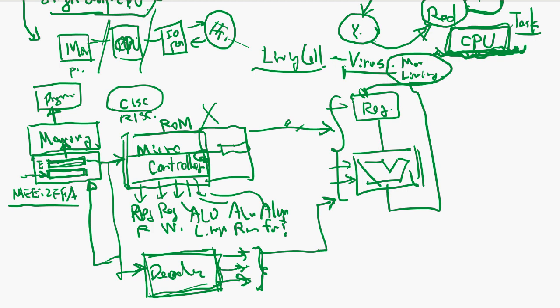And if it's a jump instruction, you calculate using the ALU and change the address here, and request to fetch the next instruction. On the next instruction, the fetch request comes, the memory interface goes to get the program instruction, comes back to this instruction register, and that is decoded, and it does the execute.